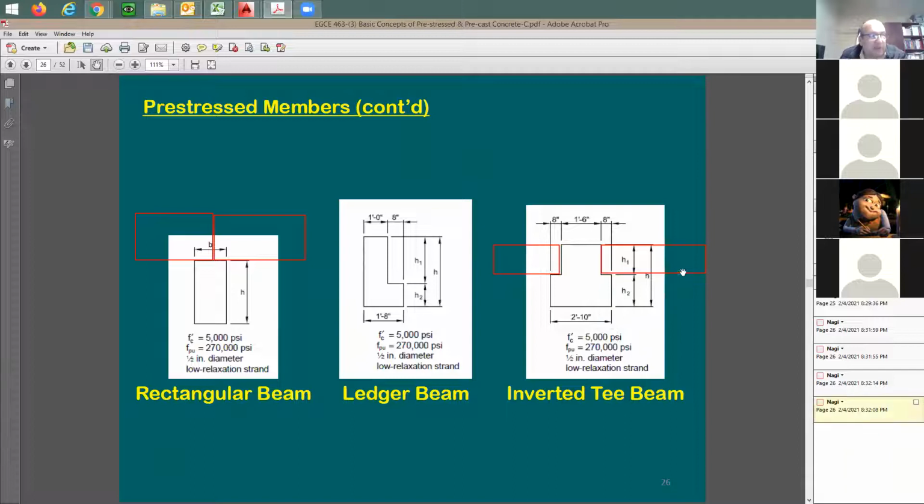According to the other picture that we were looking at, also the double T can be like this, if you like. Let me use this tool. It's going to be like this. It has a notch, right? It can be something like this. Here's a double T. Then you have another one coming from the other side. So it depends on the precaster. Each precaster again has their own details that they'd like to use. Same thing here. This is going to be when you have only a double T from one side. So you can have maybe something like this if you want to, or you can have it with a ledge. You can use this as a ledge, and you can do a notch. If you like, this is going to be a notched double T. So it depends on the use.